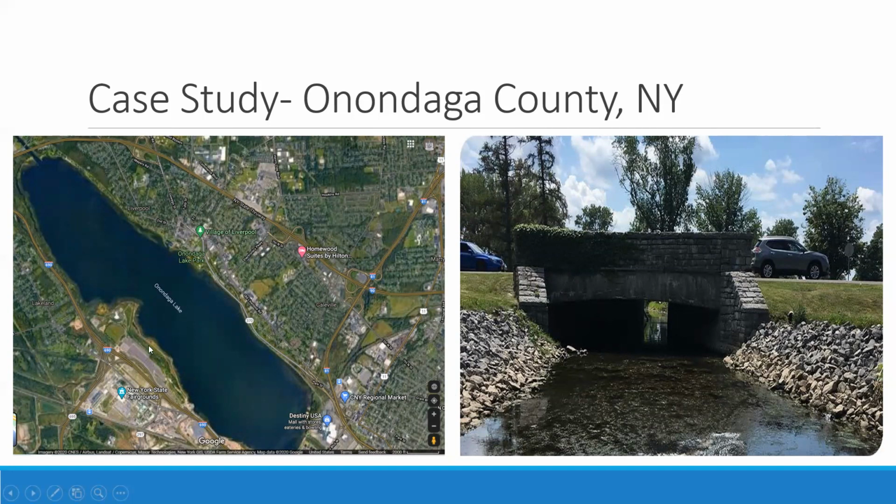So here's an overview shot of the project area. Actually, here on Highway 370 is where this culvert is located. And it was also important during the rehabilitation to maintain the profile view of the structural barrel, which had been lengthened and changed during past road widening construction. In order to do this, our design team faced the challenge of transitioning from a 234-inch diameter span at the inlet to a 174-inch diameter main barrel while navigating a 20-degree bend. We can see, kind of looking through there, the profile of the structure.